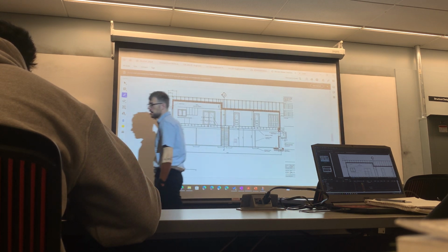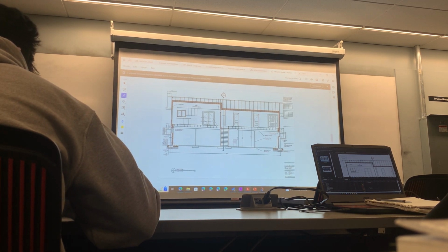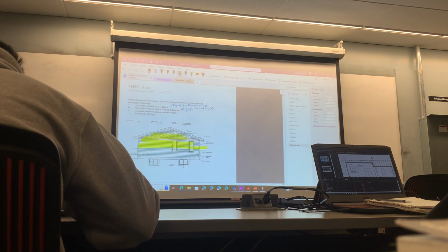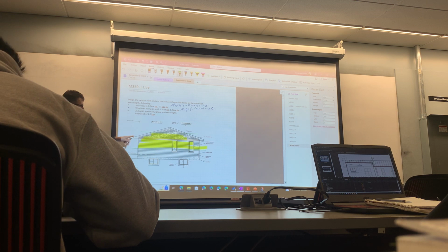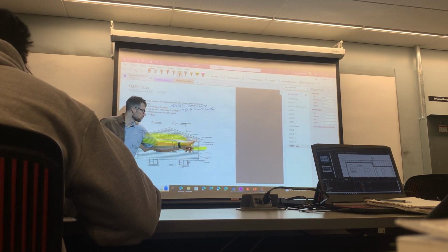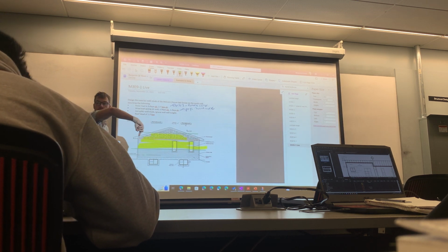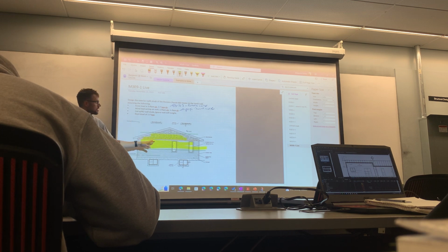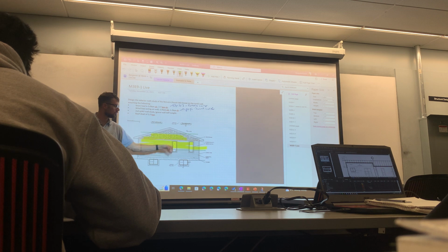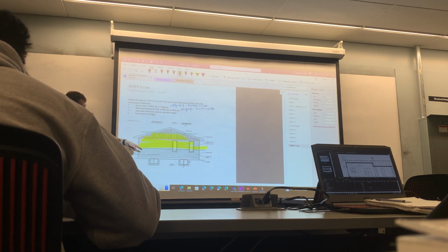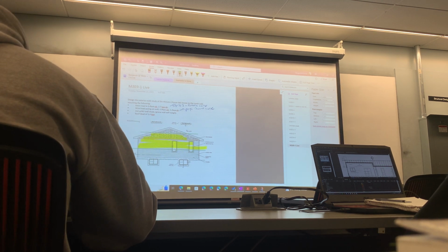The other way is on this section, this becomes similar to a beam, a bending member, and it has a reaction here, and the whole thing is bending into the page. So that's why what we'll do instead is build a rake wall all the way up to the top, and then we'll design those for bending.